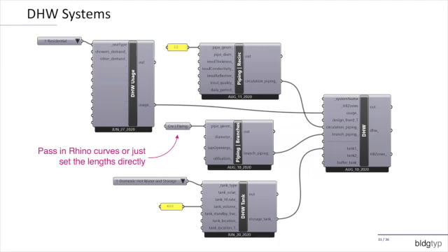The tool here allows you to do multi-zone models, which we'll talk about in a second, where you can have a different domestic hot water system for each zone in the model, and have these things combined together in all sorts of different ways. So you can build reasonably complex mechanical systems, both on the ventilation side and on the domestic hot water side.